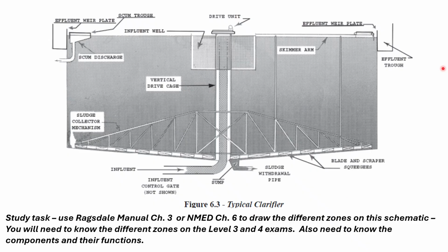This is a cross section of a clarifier sedimentation basin. The one thing I'll point out is a clarifier really is just a sedimentation basin. It's where solids settle out from a liquid waste. The suspended solids will settle out into a primary clarifier, and although the secondary clarifier does have some biological activity taking place, it is still a settling basin or a sedimentation basin. So when you hear clarifier, it's typically synonymous with a sedimentation basin.